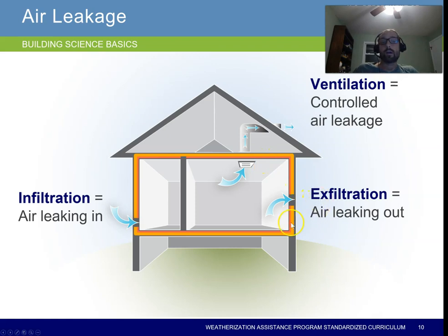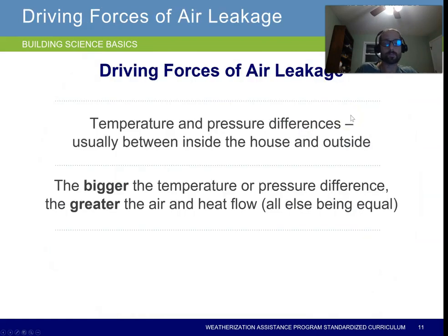There's also a difference between infiltration, which is air that leaks in, exfiltration, which is air that leaks out, and then ventilation is when you control the leakage, right? So like a bathroom fan, a kitchen fan, those are ventilation. On HVAC, which we'll talk about later, we need to provide enough fresh air for people in the building. And so that's ventilation as well, because you're purposefully bringing in air. But you do want to jot down these 3 terms: infiltration, exfiltration, and ventilation.